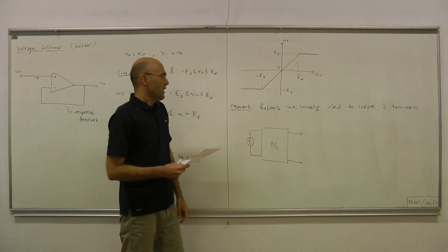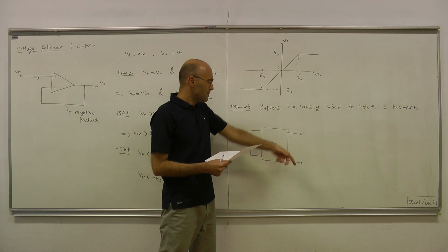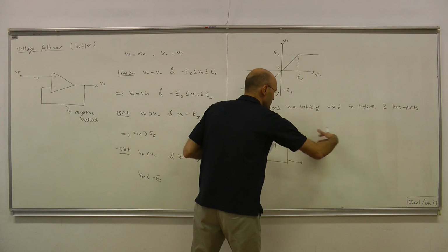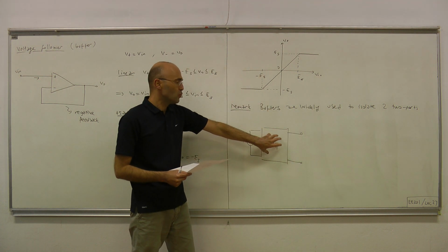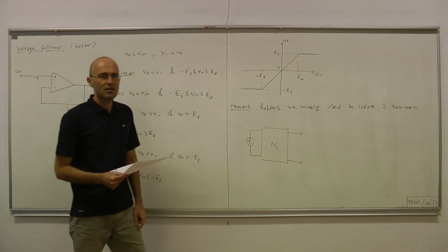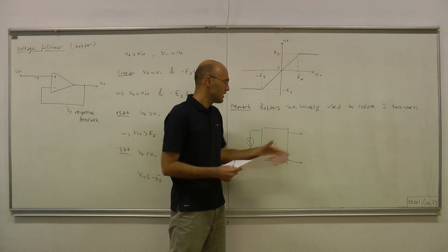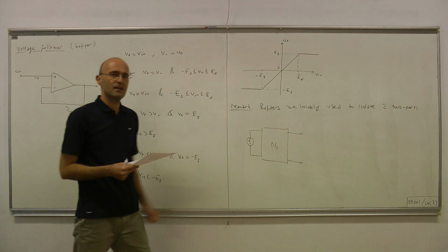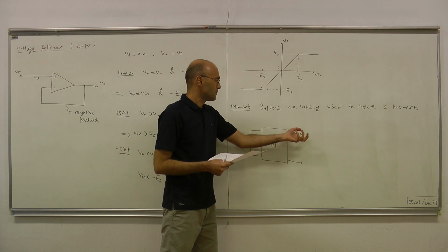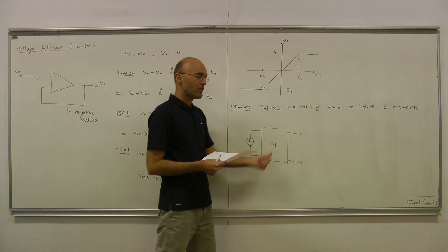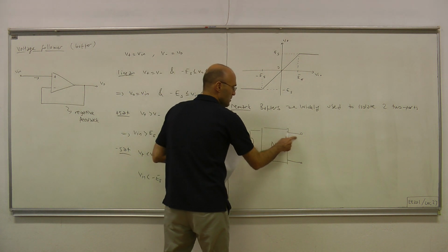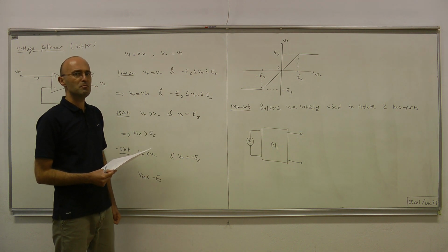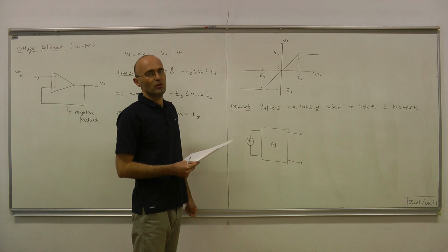Then clearly, under the assumption that this pair of terminals is open circuited, when you connect some other device, some other 2-port to this, the whole circuitry changes, because this is no longer open circuit. The circuit that you connect to this starts getting some current from this 2-port, and then when there's some current over that wire, this is no longer open circuit, and your design condition breaks down. Therefore, your design may not be successful at that point.